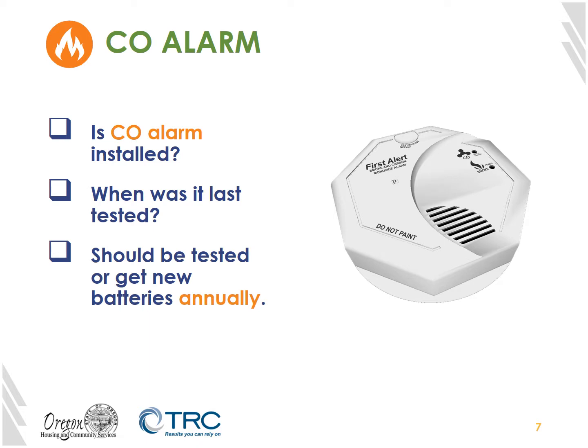One place that people have probably heard of CO is a CO alarm. So remember, CO is carbon monoxide. When we're inspecting CO alarms, first of all, we need to make sure that we have one installed. We should also know when it was last tested and ensure that they're tested or get new batteries annually, because we want to ensure that if there's carbon monoxide in a unit, the resident is alerted.